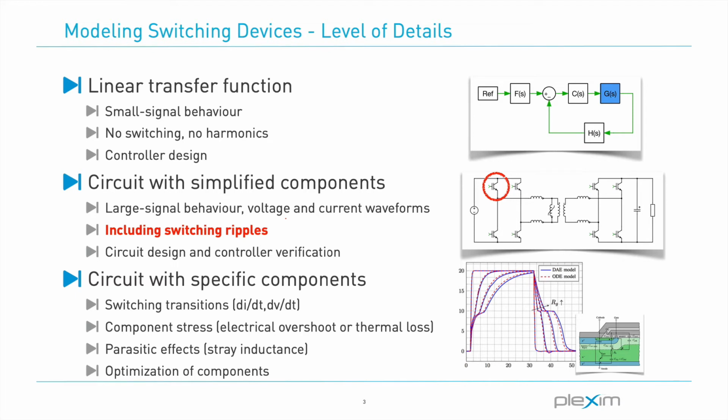On the model side, the most important one is the implementation of switching devices. Now, clearly, modeling a system with a linear transfer function will reduce computational effort and decrease the time for the HIL simulator to respond to an applied signal. However, the accuracy and flexibility is not enough for what is needed in a hardware-in-the-loop setup.